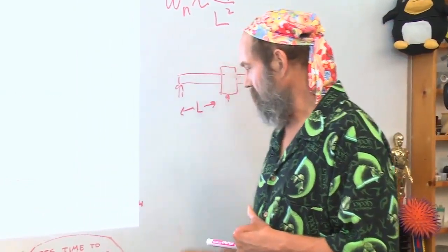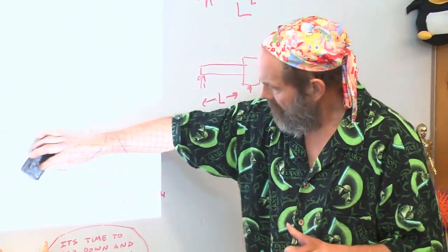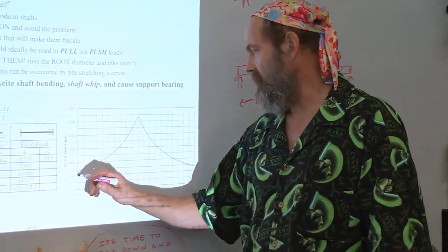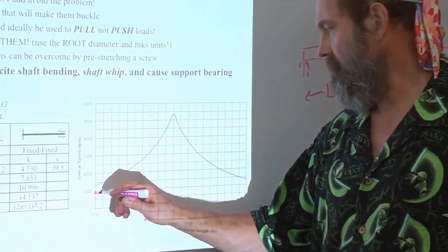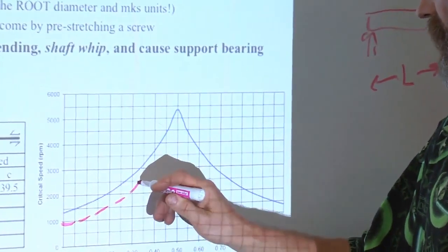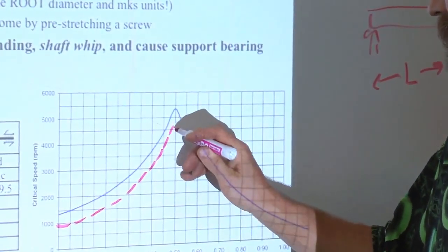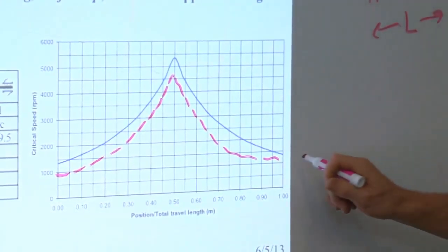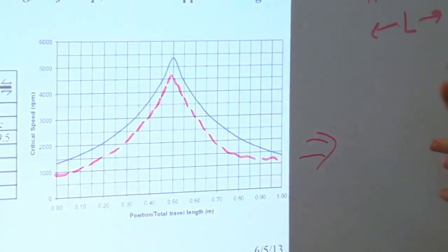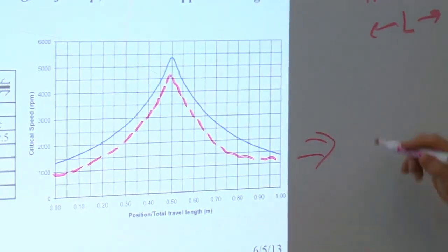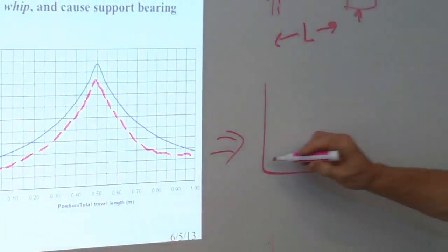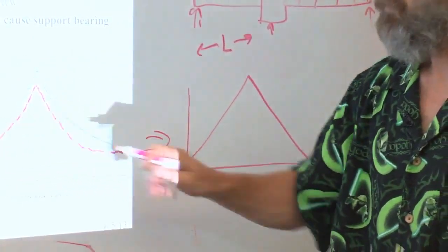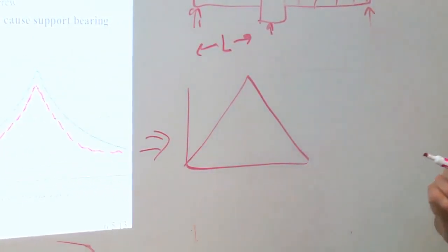But we notice now that this kind of triangular shape implies that as long as the motor is going at a speed just below this curve, and the controls people will tell you if I want to go from A to B as fast as possible, for a real physical system, you typically use a triangular velocity profile. Lo and behold, the two are relatively close together.